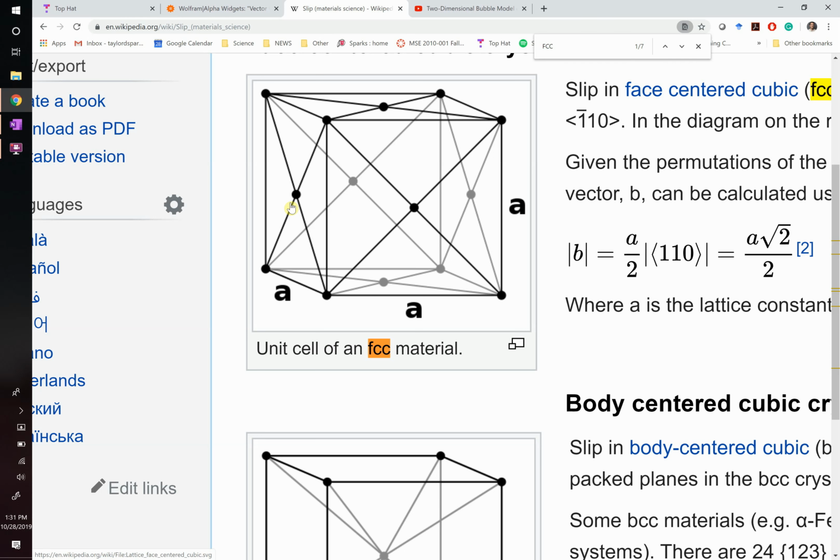Yeah, question? Why didn't we count the other ones? Like, why did we double count those? Because technically in the lattice, we can define the planes however we want, but if I start pulling on this thing, there's only those 12 that are the lowest energy things to slide along. So it doesn't matter how I defined my planes. Even though two planes shared the same line along the bottom, it's still just one direction that we actually have to pull on. In the crystal, there are 12 directions that are the lowest energy to slide along. So we'd say that there are 12 slip systems here, okay?